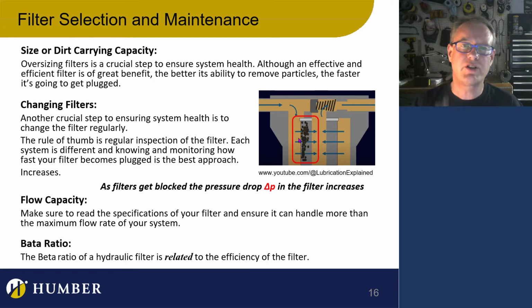So I am losing pressure across any filter, even brand new, right out of the box, right out of the factory, not a stitch of particulate in it or any dirt at all. There's going to be a pressure loss, and it will actually be rated on the filter. When you buy the filter, it'll show you a particular pressure loss at a particular flow rate.